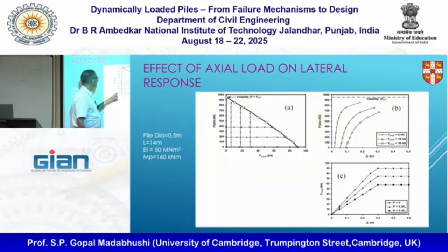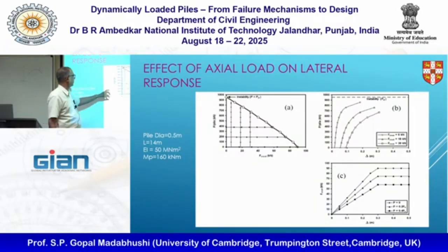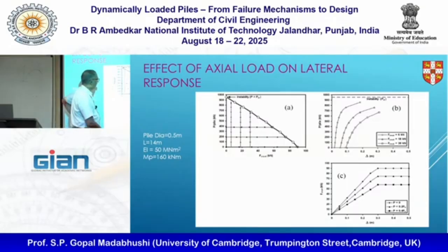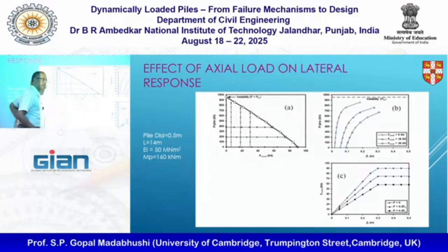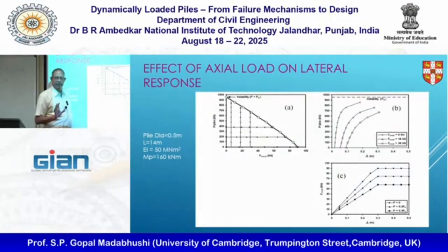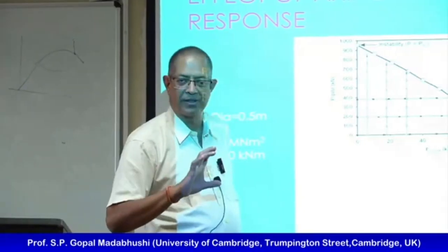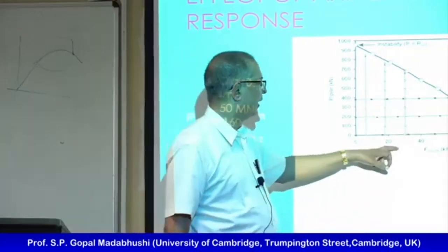Here we are doing the load per pile. This depends on whether you have a 2 by 2 pile group, 2 by 3 pile group, whatever it is. You work out the load the group is carrying, but then you work out the load per pile. And on the x-axis, we are looking at the force the crust can apply. 1 meter thick crust, 2 meter thick crust, you can work out how many kilonewtons it will generate.